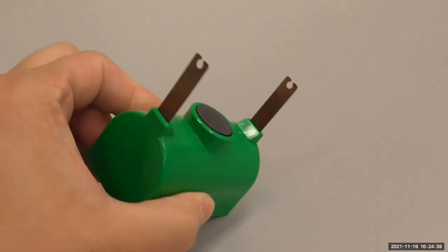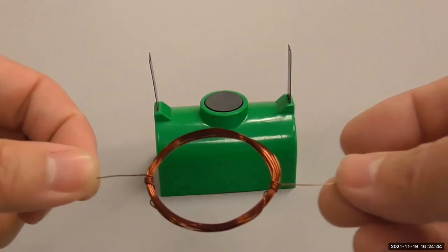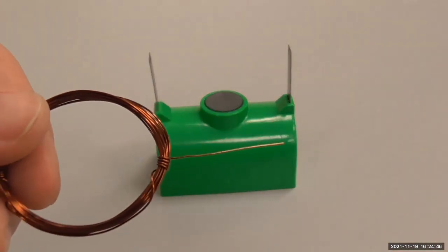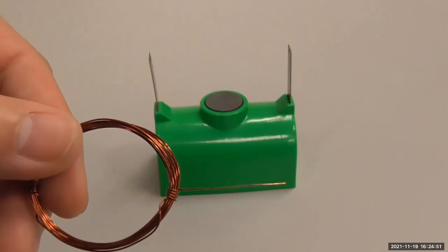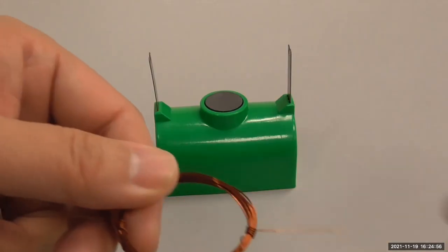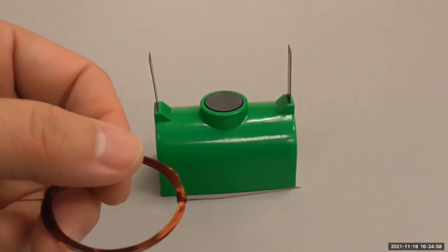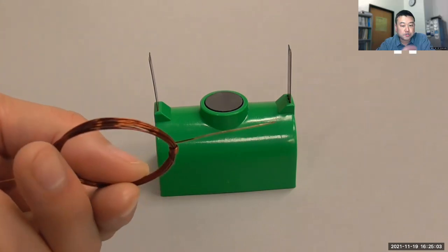Oh, I wanted to show you the electrodes for some reason. Okay, that's the coil of wire. It's enamel coated, so it's insulated between each loop. Now, at the end, if you look at it carefully, you'll see a little bit of a sheen. That's where the enamel has been stripped off. Now, it might look like it hasn't been stripped off uniformly, and that is on purpose. If it's stripped off perfectly uniformly, then the motor shouldn't work, technically, because the net torque over a whole rotation adds up to zero.